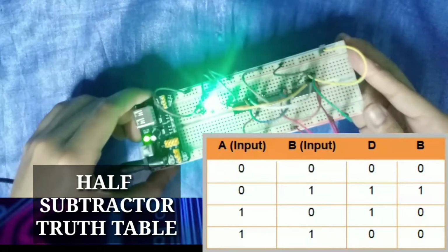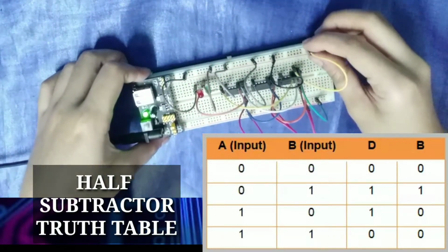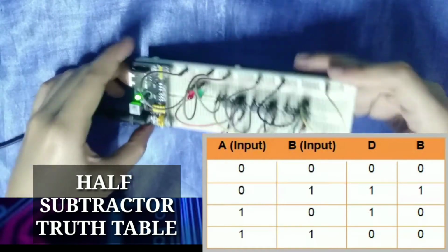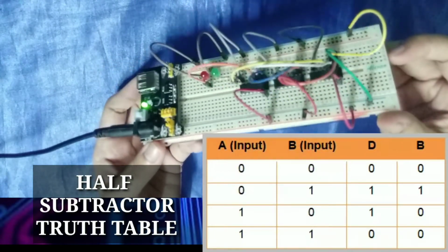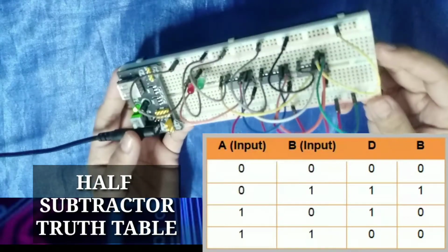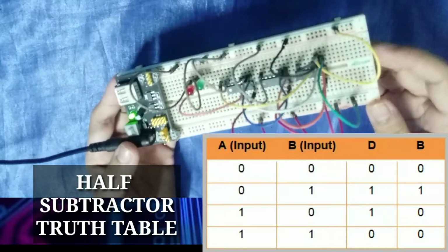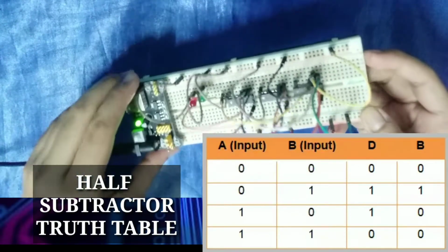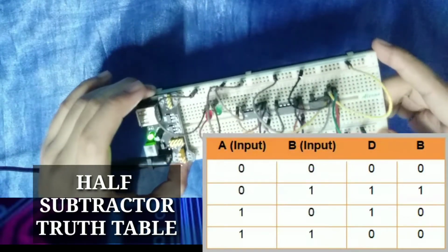Now, if both of the inputs are connected to the ground, or their logic is at 0, as you can see, both of the output LEDs, green and red, were turned off, meaning the difference and the borrow output are at logic 0. So that's our truth table for the half subtractor circuit.